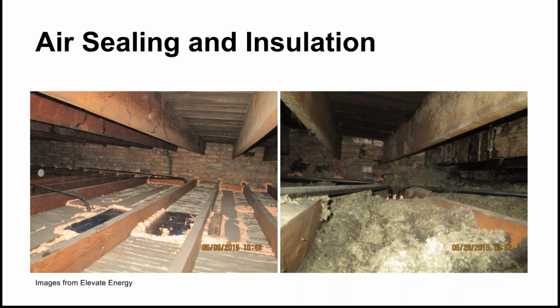Generally, insulation materials have millions of tiny air pockets to slow heat transmission. So things like fiberglass, cellulose, and expanded polystyrene, which you might know as styrofoam, are all really good insulators because they are full of tiny pockets of air that make heat transfer really slow.